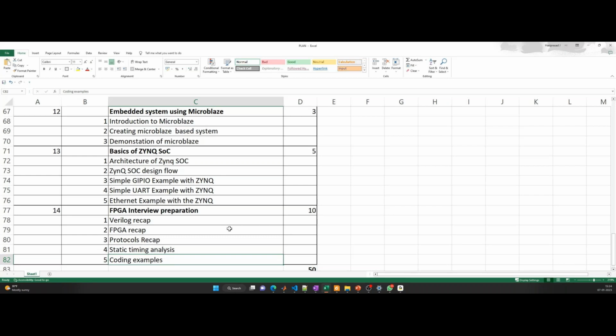One thing you should understand: in the ASIC flow there will be separate STA engineers, separate simulation verification engineers, separate physical design engineers, and separate test engineers. But as an FPGA engineer, you will be doing everything by yourself, from the stage you are writing RTL to bitstream generation.